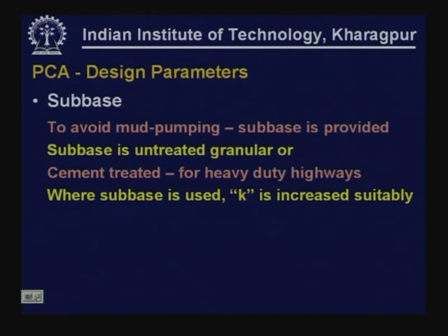We may provide subbase to avoid mud pumping. Subbase can be untreated granular base or cement treated, especially for heavy duty highways, high volume roads. So, normally we provide granular subbase untreated either with cement or asphalt or bitumen. So, that is what is known as granular subbase, or we can also have cement treated base.